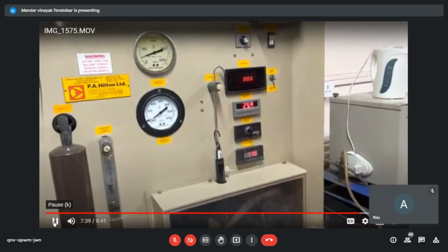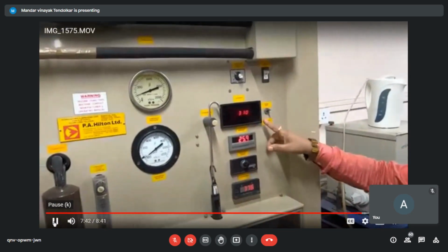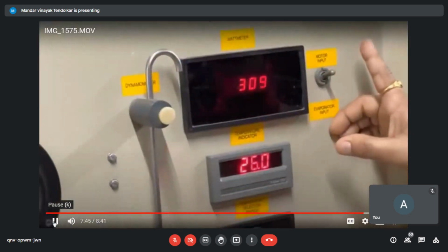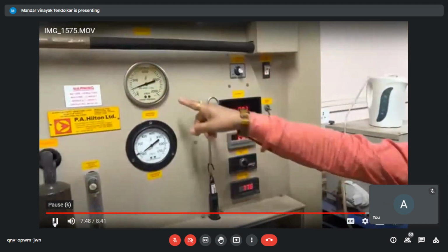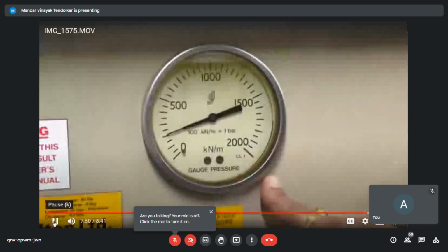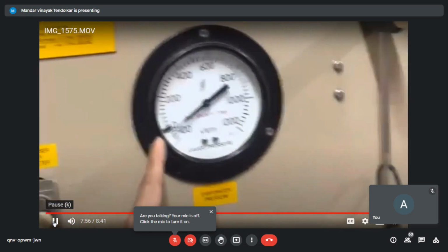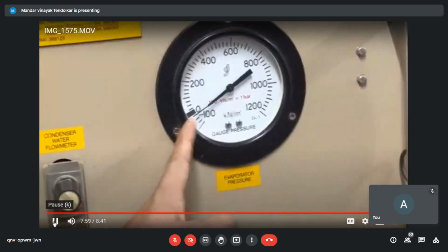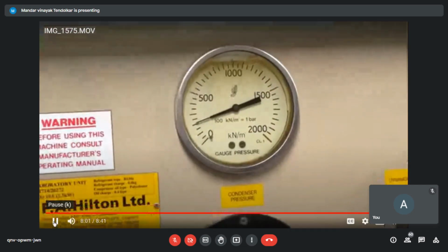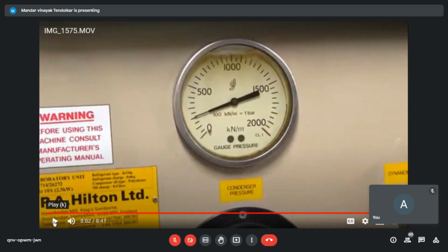नंतर हे घ्यायचंय, मोटर इनपुट. See, motor input is 3112. Then the pressures, the condenser pressure is around 200. Evaporator pressure is minus 25. Minus 25 kPa, this is plus 200. Are you getting it? This is plus 200 kPa condenser, and evaporator जो नीचे है, that is minus 25, zero के नीचे. So this is how we take the readings. Any problem to anyone? No, sir.